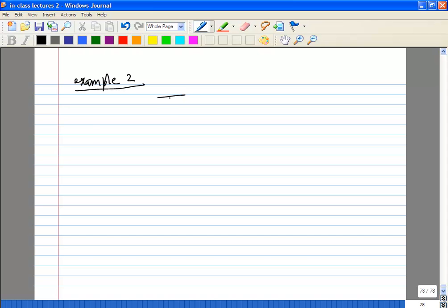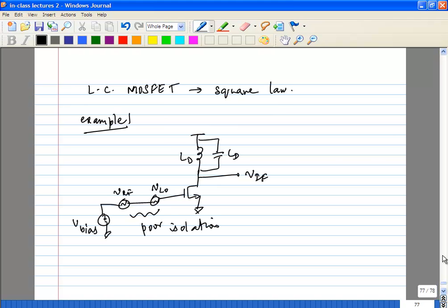Let's see how we can modify this. The output there was no problem. Effectively, you're connecting RF and LO in series, so it is very easy for your LO to leak through to your RF signal. Remember we had a problem when we considered the original mixer to be 3-port. Your LO signal is going to be very large and your RF signal very small, so it's very easy for LO and RF to interact with each other.